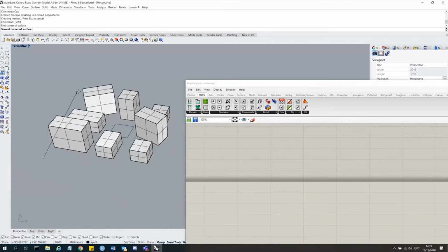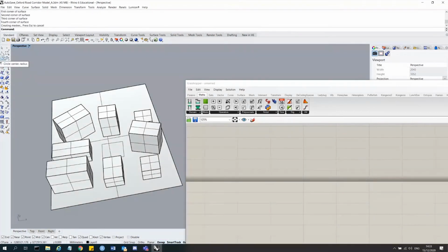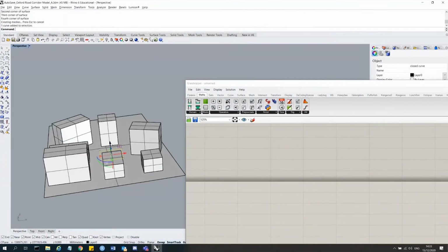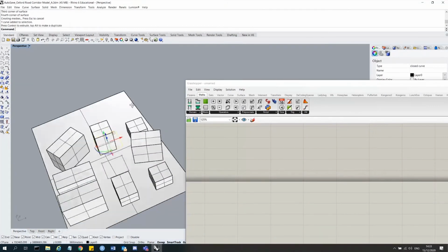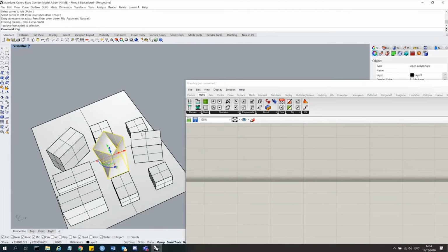And I just want to give it kind of a surface here, so it's not floating in midair. And let's do something funky for that tower. So I'll just move this up, like this, rotate slightly, and then I use the command Loft. Select curves to loft, so I just select this one, enter. That's fine, enter. Okay. And I want to cap this as well, so Cap.